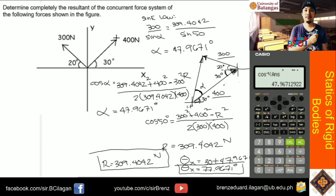Okay? So let's first analyze the 400 Newton load. Again, it is acting at an angle of 30 degrees, which means it has a y and an x component. If its direction is like this, where is its y component? If you split it in two, its y component goes upward, and since it points this way, its horizontal x component goes to the right.